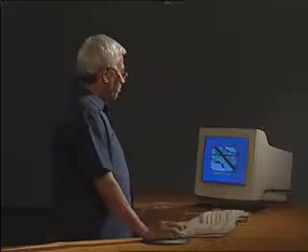No sync, the picture will be unstable on the TV screen, and this is one example where the combined sync is missing, and we get a picture on the TV screen of this type, where horizontal and vertical both are missing and the picture is rolling horizontally and vertically both.